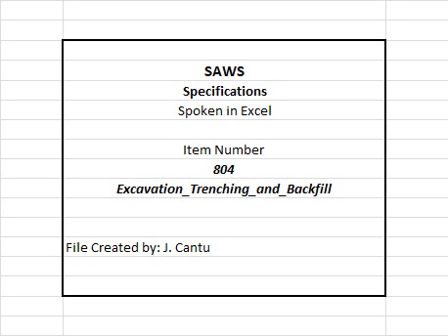7. Submit emergency action plan, EAP, to address contingency plans in the event of damage to utilities. Include the following. A. Contact personnel and agencies including primary and secondary telephone numbers. B. Contractors' hierarchy of responsible personnel. C. Traffic control measures, and D. Identification of resources to be available on or near project site in event of damage to utilities. 8. Submit backfill material sources and product quality information in accordance with requirements of this specification.